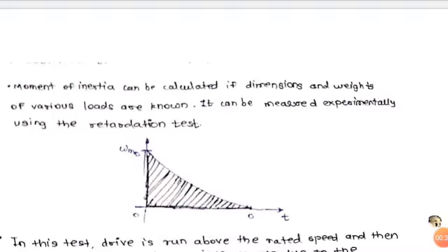Now, as we know, previously we have already derived the fundamental torque equation, which is T minus TL equal to J d omega m by dt. So the J term is there in that torque equation, and J d omega m by dt is the dynamic torque which plays a vital role in the dynamics of the drive.